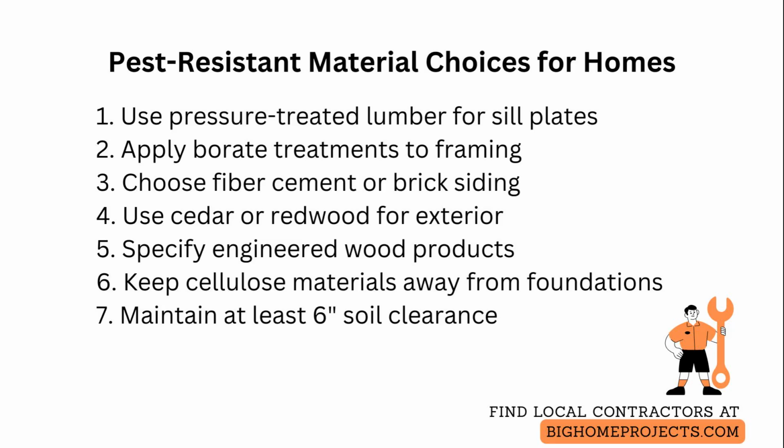Use borate treatments on interior framing and roof framing during rough carpentry to protect against wood-destroying insects and fungal decay, applying according to manufacturer directions and keeping treated areas dry to maintain effectiveness.